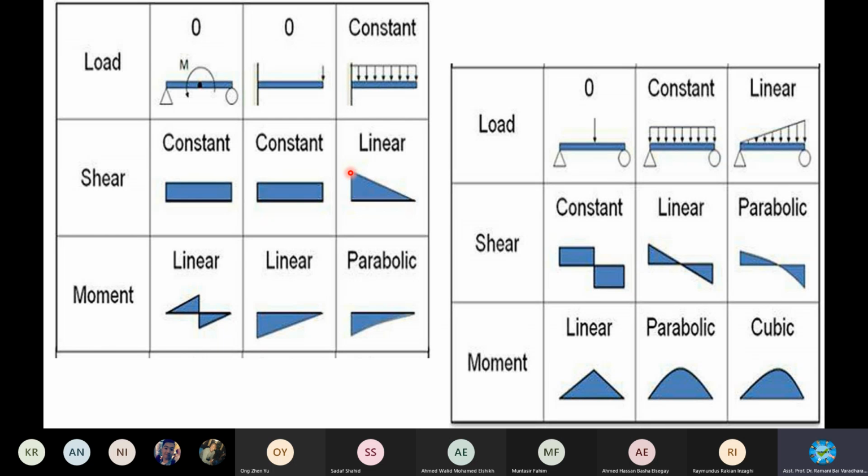And then moving on, there is a loading and a response. Why is it tending to incline in decreasing? Because there is no other support or reaction here. So naturally it will gradually reduce to 0 at this point at the free end, because it's free. In these cases you have some loading, in this case you have some reaction, in this case it's free. That's why it is going on reducing. There is some UDL here, going to 0, no UDL at all. That's why it is reducing to 0. You have an inclined line.